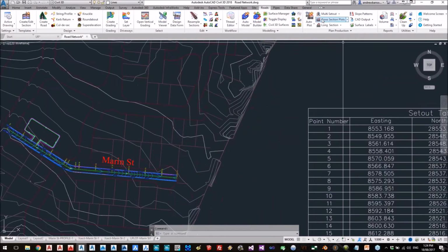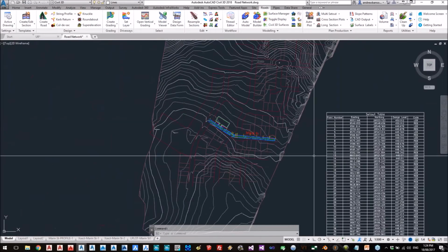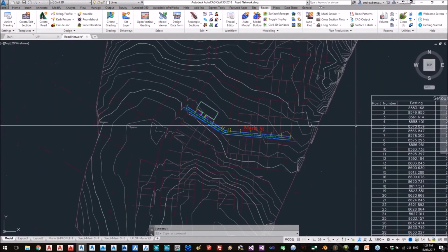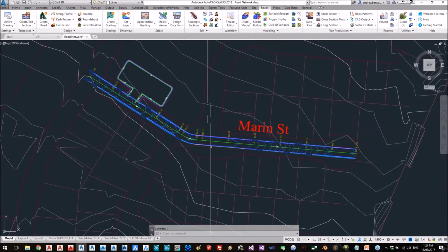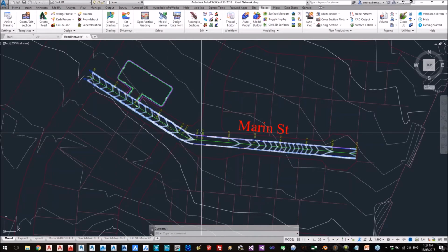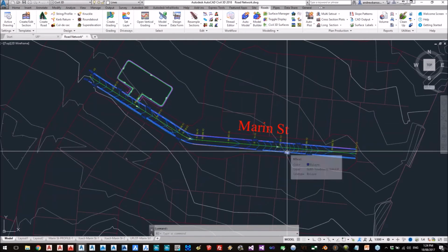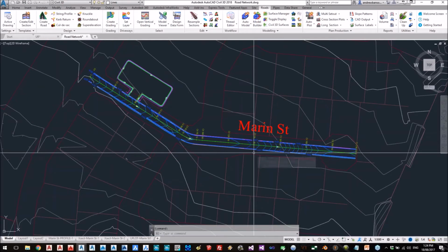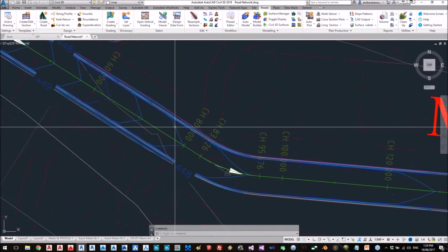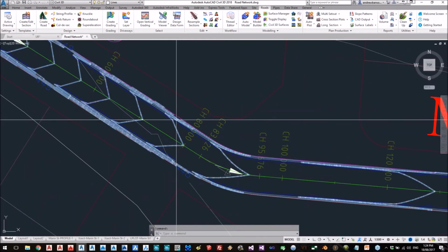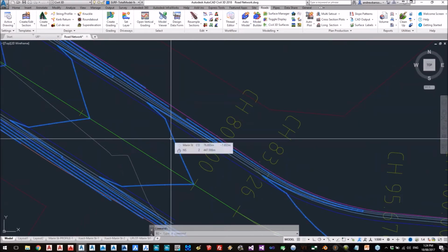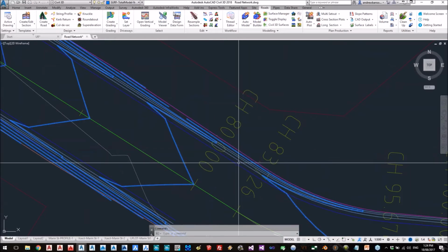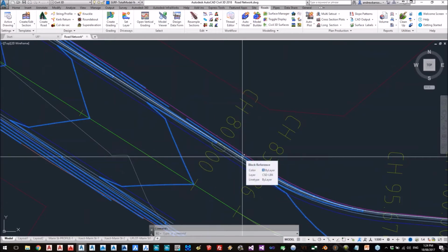Now, for Marin Street, I've used multi-set-out, and I've actually done a set-out. I've turned the set-out points off for now, but I've outputted the set-out. So I want my thread to go and update the set-out. I might also add to the thread a cross-section update and a long-section update, and maybe we'll do some CAD outputting plan as well. So the line work I see here, just the auto design, auto line work, but I'll have the software output the contours as 2D polylines, and my other line work here is 2D polylines as well.